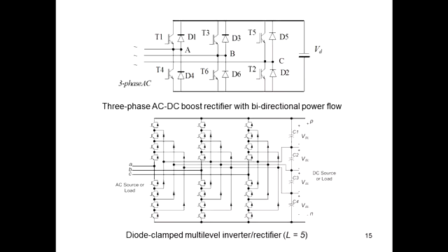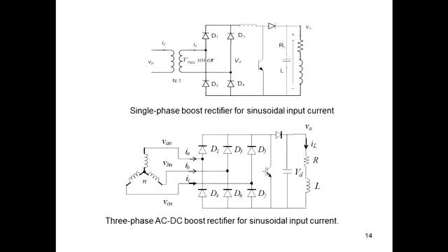These are diode rectifier circuits with a boost converter that makes the current waveform sinusoidal here. So this side, the AC side, where the energy comes into the circuit, becomes of unity power factor. All right, it could be the AC generator, which is supplied by the wind turbine. All right, the wind turbine has the generator, and that generator has an AC output. That can be rectified in this way, and then, using the boost converter, we can operate it at a unity power factor. Not only that, we can produce a certain voltage which is consistent with coupling that source to the grid, okay, through an inverter.